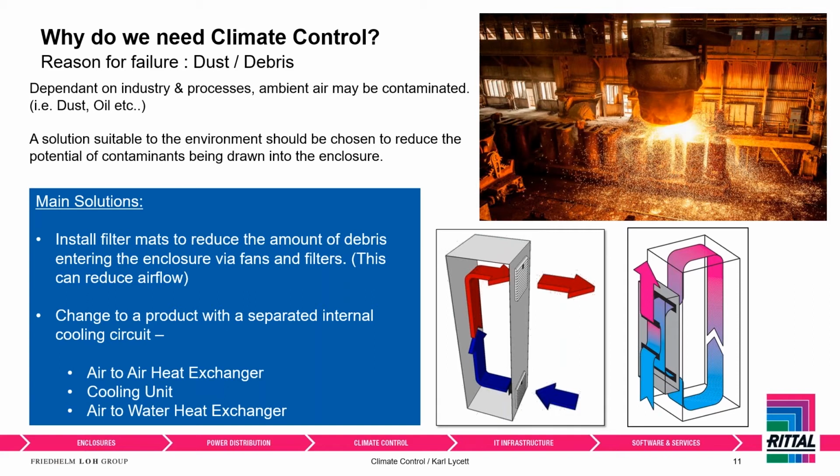So fans and filters do have a worth. They have a place where they work correctly, but you need to use them in the right manner. So if you are using air cooling, you are using fans and filters, you need to be installing filter mats, because that will reduce the amount of large debris that gets inside the enclosure, okay?